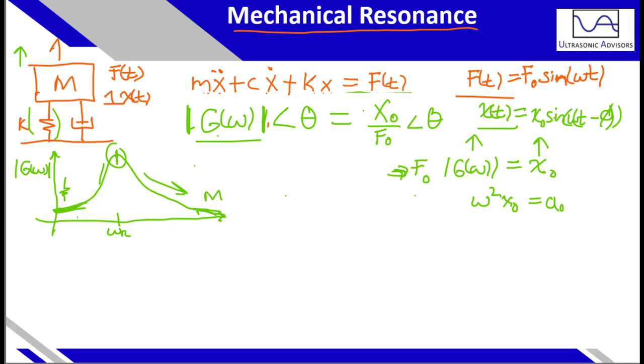So the result of that will be a higher peak. And the peak will also be more sharp. It'll also be of a larger amplitude. So this describes the input and output forces. So input force, output displacement. At low frequency, it's governed by the stiffness of the system. If you have a very low stiffness system, you will also have a very high amplitude.